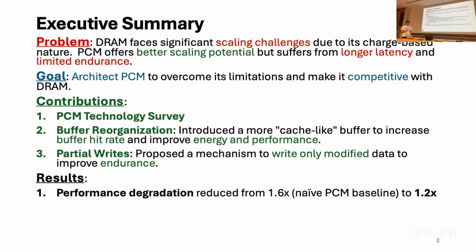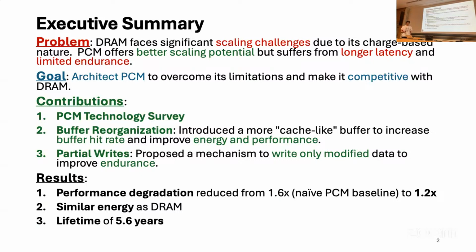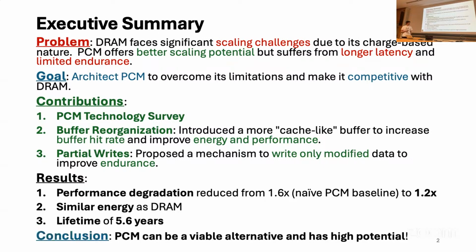The results from the paper are, first, they reduce the performance degradation relative to DRAM from 1.6x, which is a naive PCM baseline, to 1.2x. They achieve similar energy as DRAM. And lastly, a lifetime of 5.6 years on average throughout the benchmark applications. In conclusion, PCM can be a viable alternative to DRAM and is a very promising technology due to its scaling potential.